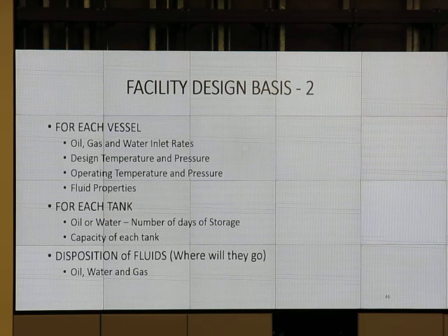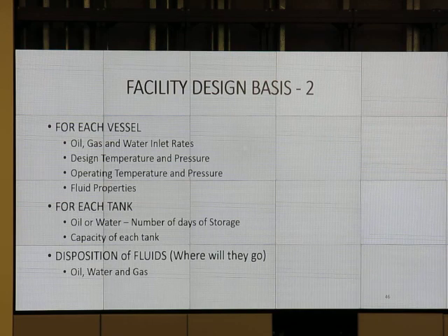And then for each vessel that we have, what are my oil, gas, and water inlet rates? You say, well, maybe going to a vessel that doesn't have any gas. Okay, the gas rate is 0. But what are my oil, gas, and water inlet rates for each vessel? What's my design temperature and pressure? And then what's my operating temperature and pressure going to be? And the fluid properties for each one of those that go in there.